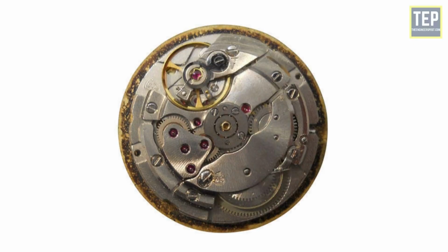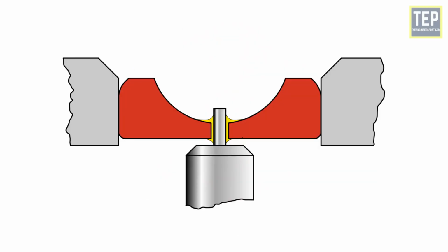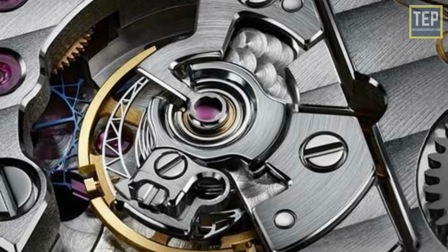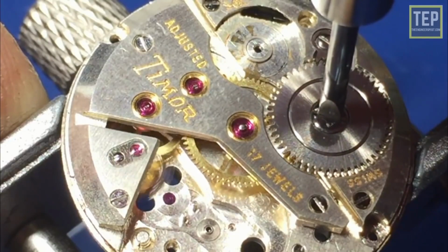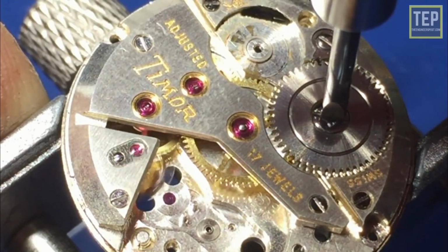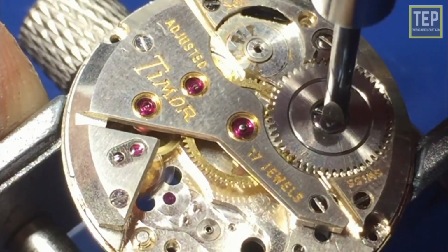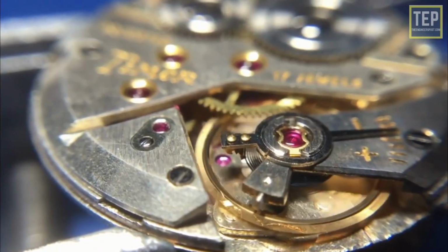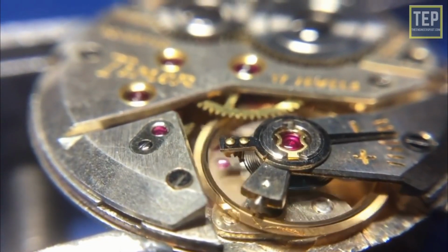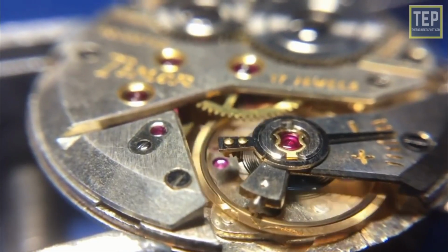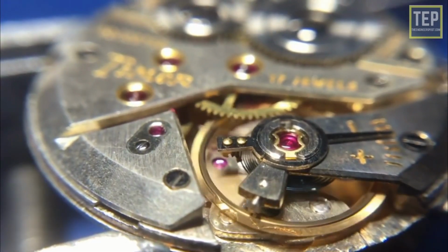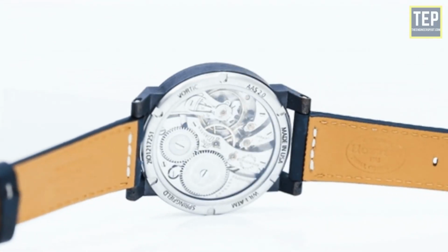A jewel bearing is a plain bearing in which a metal spindle turns in a jewel-lined pivot hole. The hole is typically shaped like a torus and is slightly larger than the shaft diameter. The jewels are typically made from the mineral corundum, usually either synthetic sapphire or synthetic ruby. Jewel bearings are used in a range of industry applications and in precision instruments where low friction, long life, and dimensional accuracy are important. Their largest use is in mechanical watches.